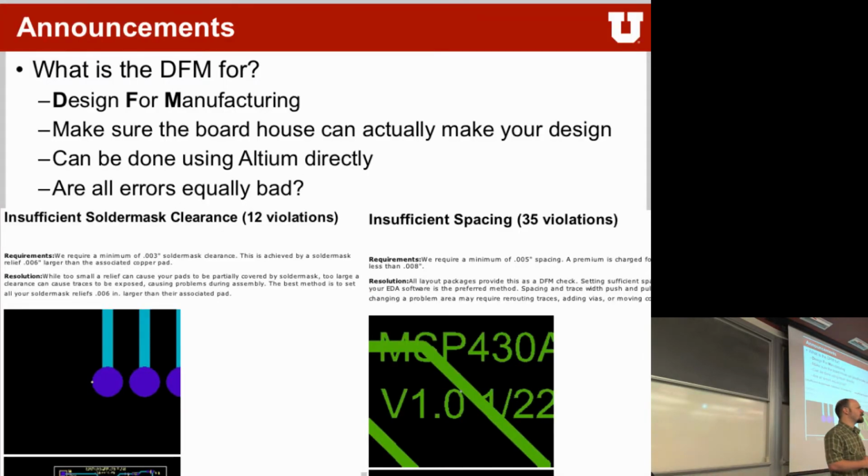You might have asked what these DFMs are all about, like the FreeDFM service that we use. DFM stands for Design for Manufacturing. So this is basically a test and a check of your PCBs telling you if this board can really be manufactured. What you saw is sometimes you had errors that were a little bit bogus and they fixed them themselves, so they were not showstoppers. Other times they told you these are actual showstoppers, which means that something is really odd or strange with your PCB design, something that they don't feel confident about that they can actually manufacture.